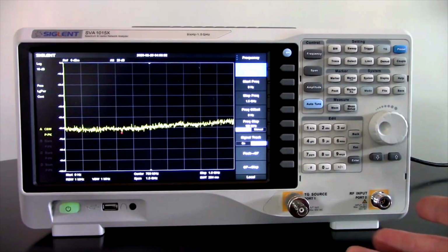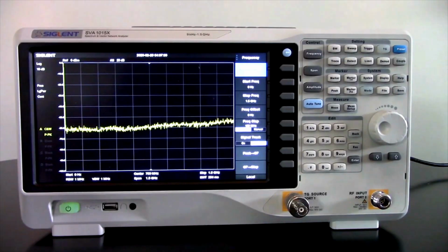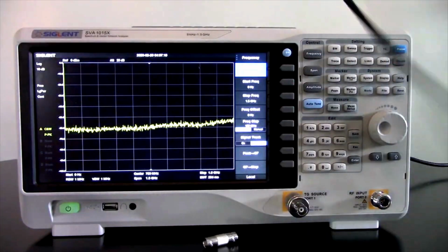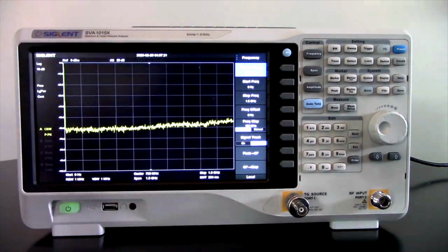Another technique is time domain reflectometry. Frequency domain reflectometry has some advantages in its position accuracy. It does have some limitations as far as the length, but if you're looking at cables around 100 or 200 feet, this is going to get you within a few inches of that fault. So that is a really nice place to start when you go hunting for that problem in a few hundred feet of cable.